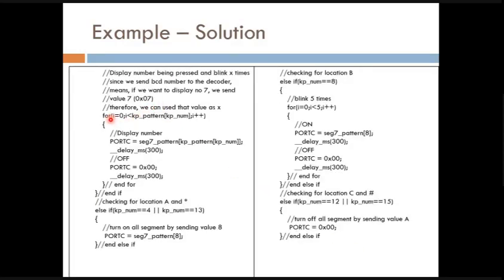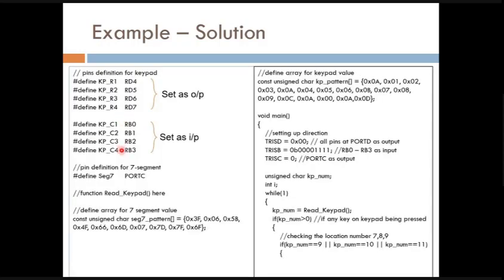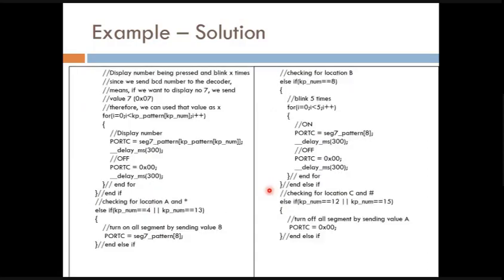So you go for another loop. You implement a for loop, starting with the initial value of I equal to 0. We already declared I. What is the I value? I is an int, integer, so the number can count up to more than 255, but not more than 65,500 and something, 16 bit.